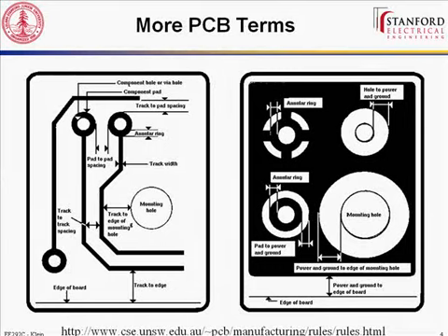For stuff like we're doing, if the biggest thing you're driving is an LED, that's maybe 10 or 20 milliamps, you can get away with an 8 mil trace and space, no worries at all. For your power traces, if you opt to do a 2-layer board, you'll want your power traces to be larger. Because going into your microcontroller, you may be dissipating a couple hundred milliamps. And coming out of your voltage regulators, you'll probably be sourcing a couple hundred milliamps. So unfortunately, it's track dependent.